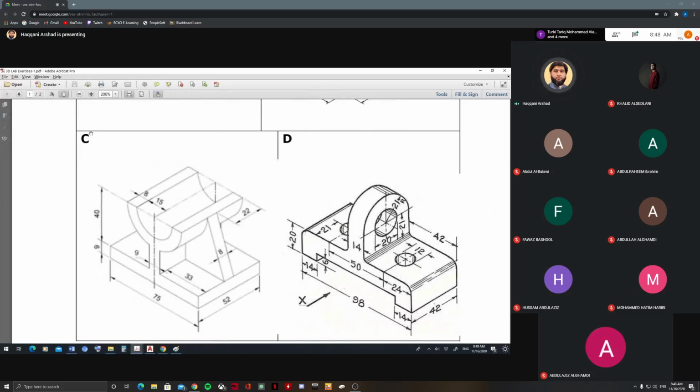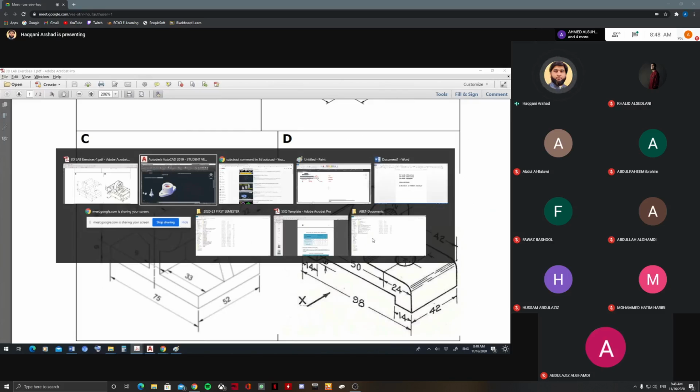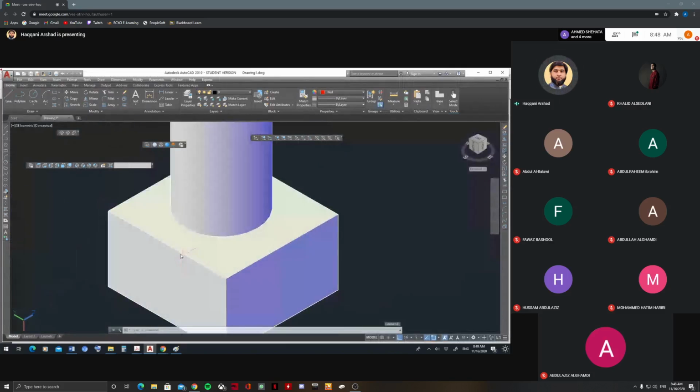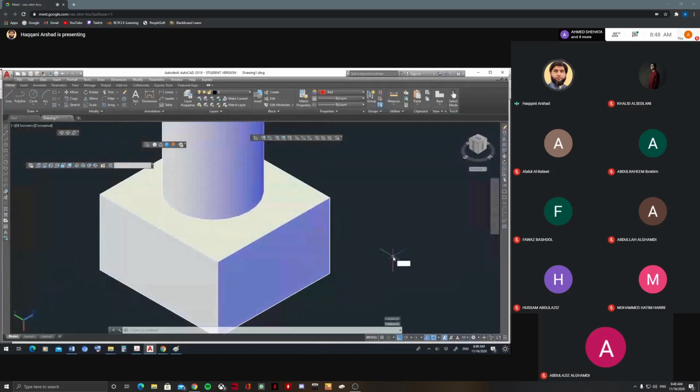This one I'll show you, the C. This is easy. D is easy. You can do also fillet. Fillet is also a command we can do in 3D. For example, here you have an object. I want to do fillet. Go for fillet. Okay. Select the object. We'll use R, enter, radius. Maybe use 2 or 3, doesn't matter. 5. Okay.